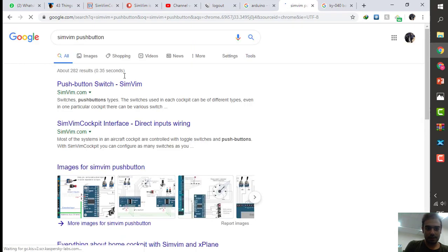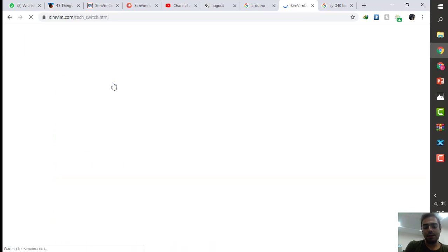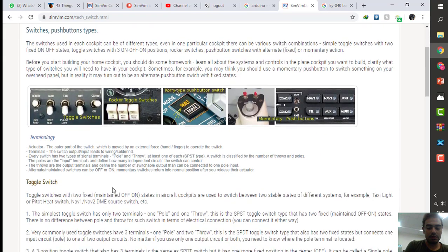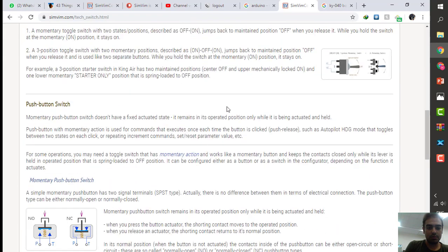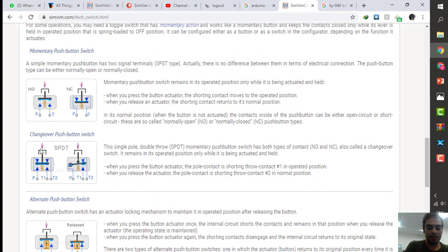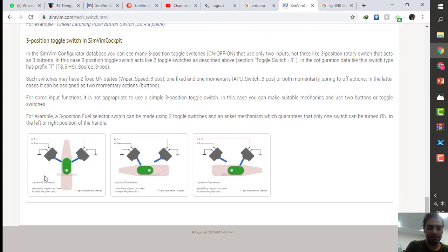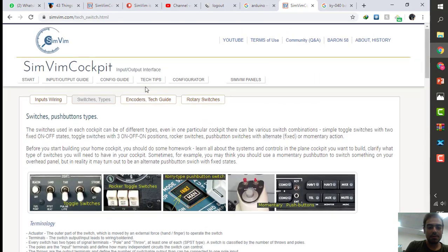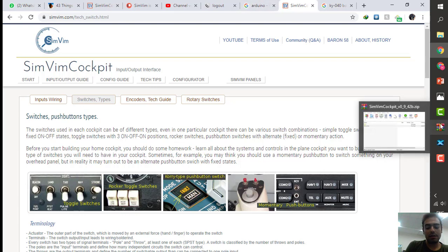This one is much easier than the last one. As you know, the switch push buttons just have two pins. They're either connected or disconnected. Very easy. Again, you have the theoretical details about them and the different modes of them, and how they actually work. You can use this page to know more about the push buttons. But push buttons are very simple. They have two pins and they are connected between a digital input of the microcontroller and ground.